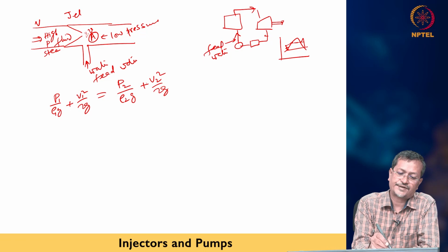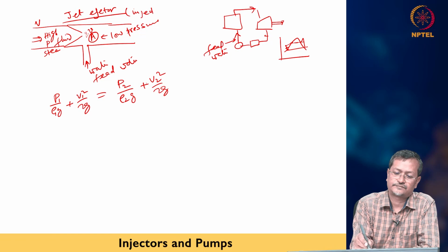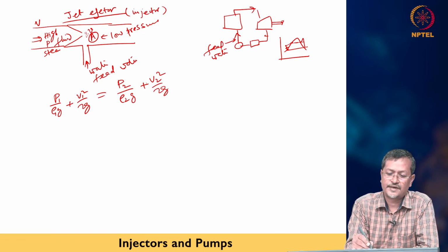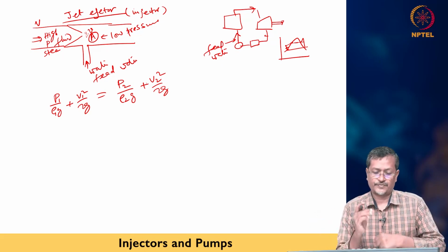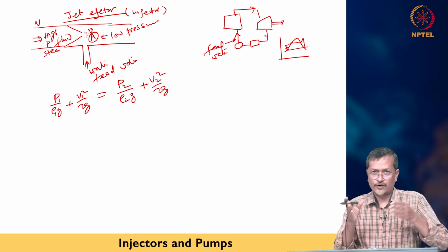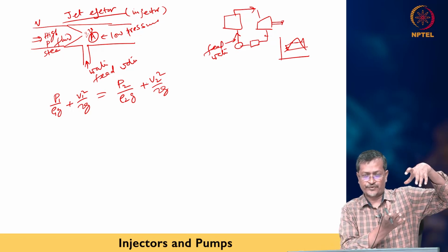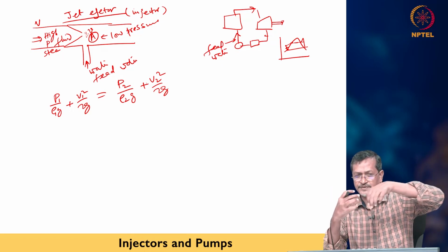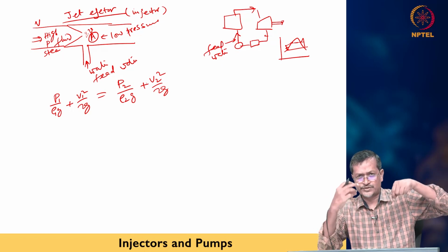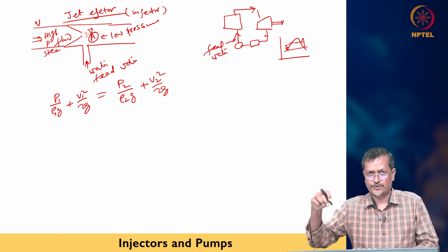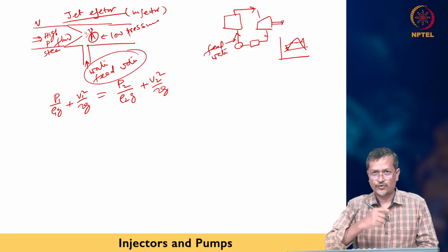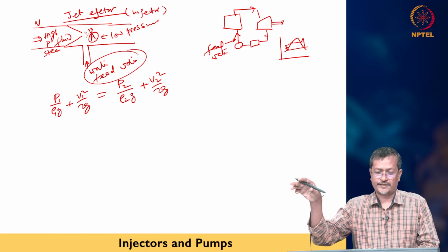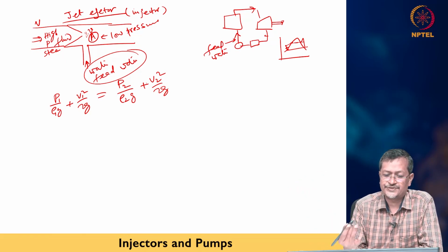This is ejector, jet ejector, injector. Okay, boiler water injector. The low pressure water will be injected into the boiler using the ejector. Okay, so you are creating very low pressure, high velocity, and high pressure fluid is there. You create narrow channel. Narrow channel means the same amount of fluid is going through a small channel. When it is going through the small channel, pressure will be dropping. When pressure is dropping, the feed water will be sucked and it will go to the boiler. Okay. So this way this jet ejector works.